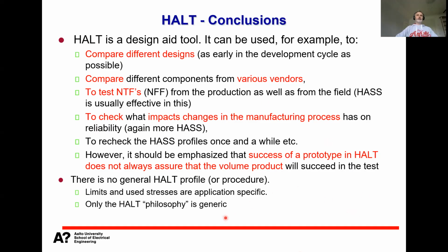So to sum up, there's no general HALT profile or procedure. There is just a philosophy, the HALT philosophy. You can use whatever stresses, whatever combination of stresses, to figure out the weakest links and then try to improve the robustness of your product.